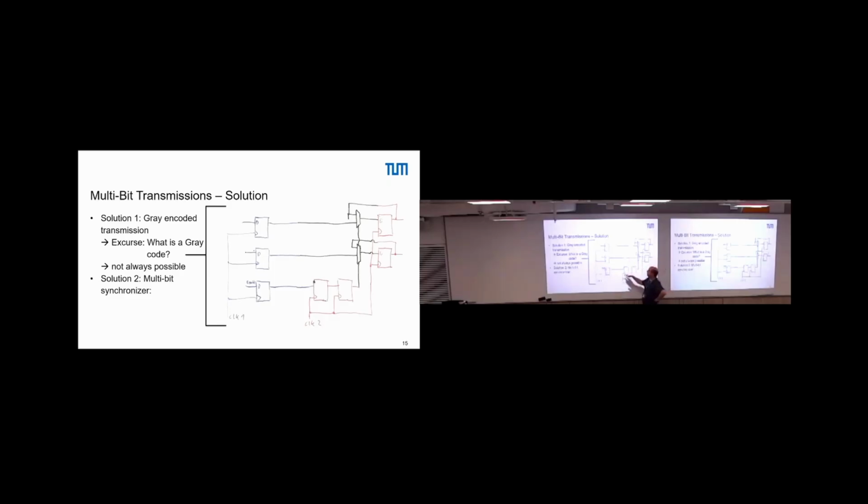So if we send the data here, with the sender clock, 1 clock cycle earlier, then we put the enable, then we can be certain that if here the enable is synchronized, is delayed, then when the enable signal arrives here at that point, we have here a stable signal. A stable signal at the input means we have no problem with synchronization. We need no synchronizer anymore.